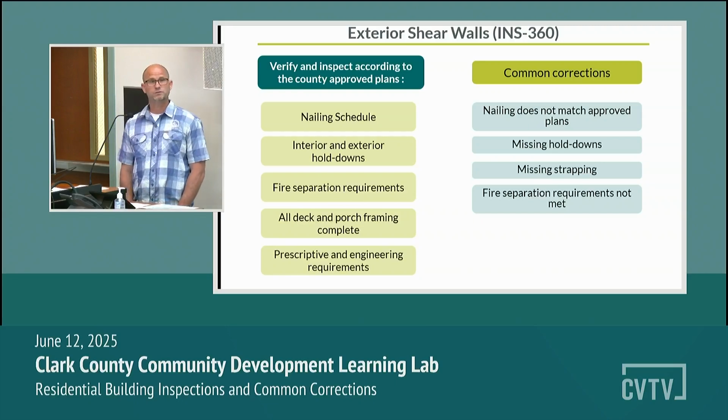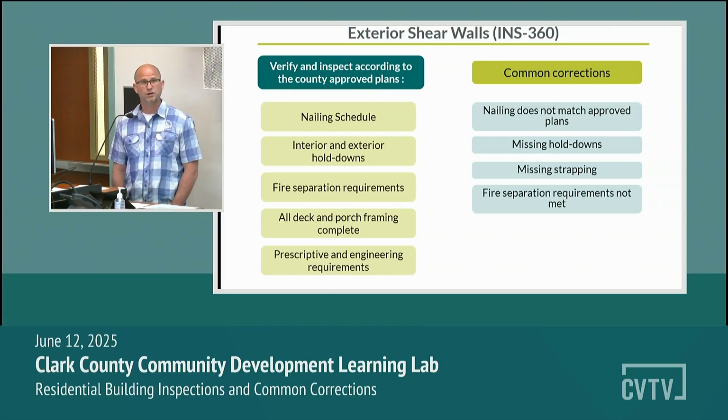Because if a hold down was missed, we like to go back to the engineer, have them write you a letter stating how they want to retrofit this, and then we will come out and we can verify that the retrofit system has been done correctly.